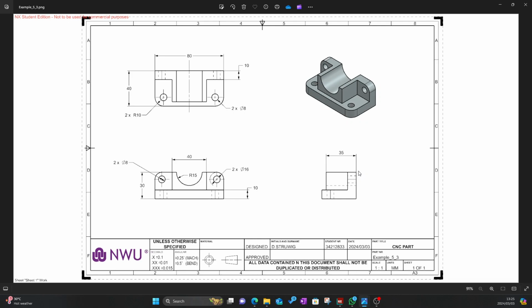For the mixed class, I've told you, you should remember that it's easiest for a simple model like this to create a block, and then from that block extrude the features to represent the final model. So here we will create the block with the correct dimensions, and then we'll extrude the features from that block. I'm going to show you the steps inside NX.